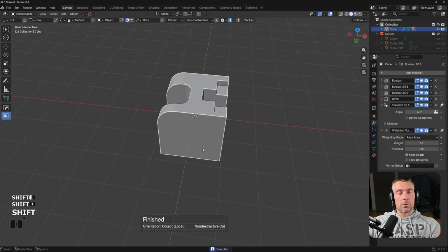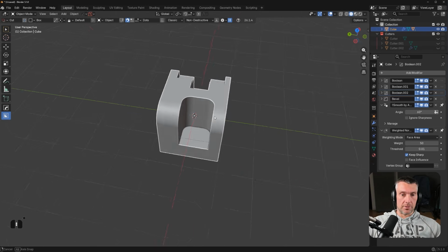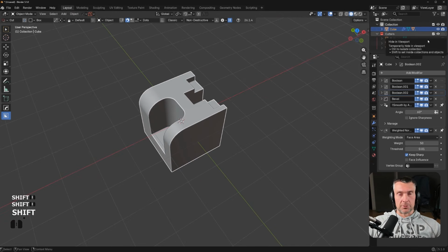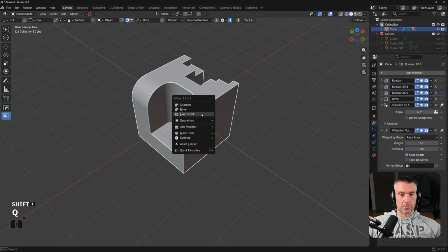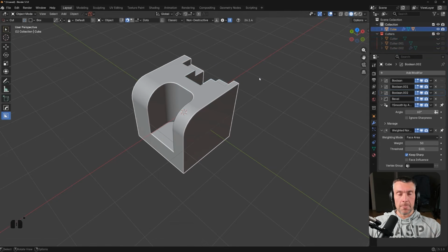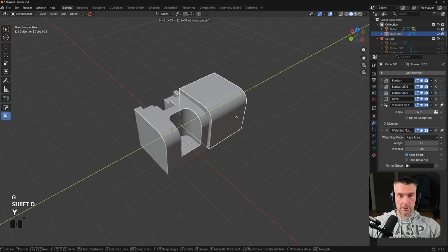Now, let's say I wanted to change one of these cutters, alter this, or move it, or create some sort of a bevel on them or whatever. Normally I would need to go here to the cutters collection and look for them, but with Hard Ops, I can press Q, go to Ever Scroll and scroll through my cutters on that specific mesh, right? What if I wanted to, for example, duplicate this mesh and move it a bit to the right? So let's say I wanted to grab this one, Shift D, and move it to here on the Y-axis.